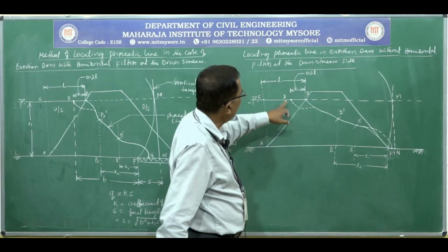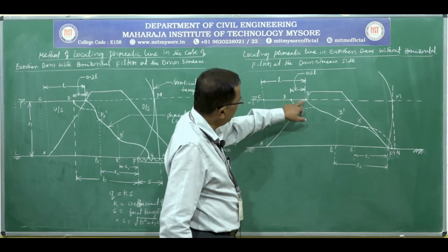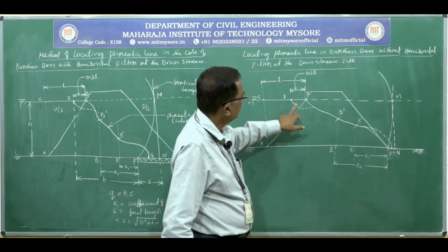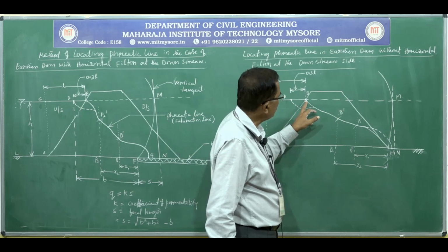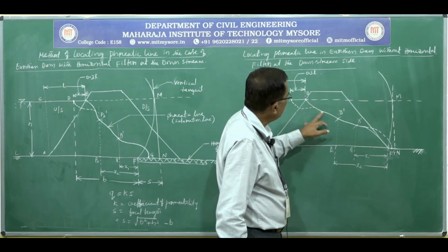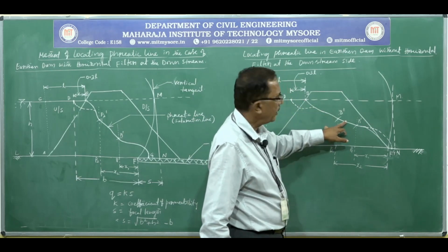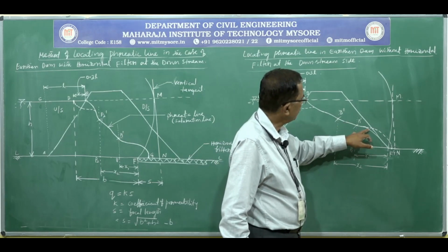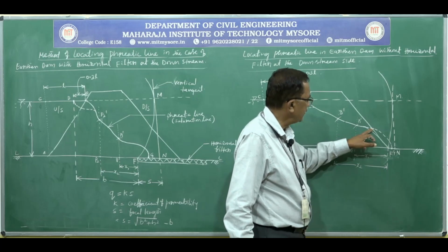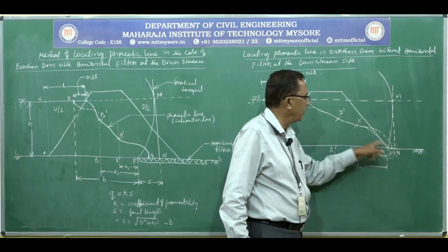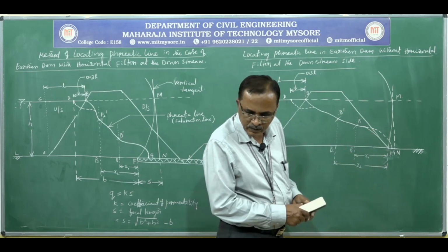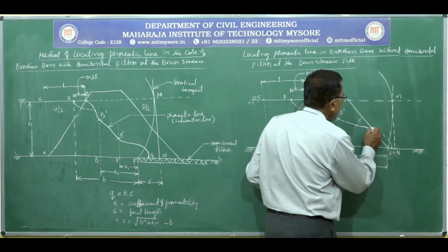so you can see the actual commencing point of phreatic line is B, not at point D. So phreatic line runs smoothly in the form of a parabola or ellipse, and there is a tendency of emerging out of the dam at a point, you can call this point J.